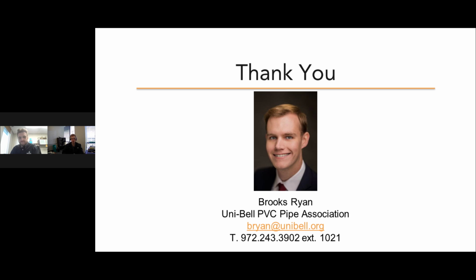So one of the things that we're working on right now is getting testing done with UT Arlington to conduct that cyclic testing for PVCO pipe, to hopefully establish an equation or series of data points to use to determine lifespan of PVCO in cyclic applications such as force mains or areas that have a lot of pump stations and high pressure cycles.